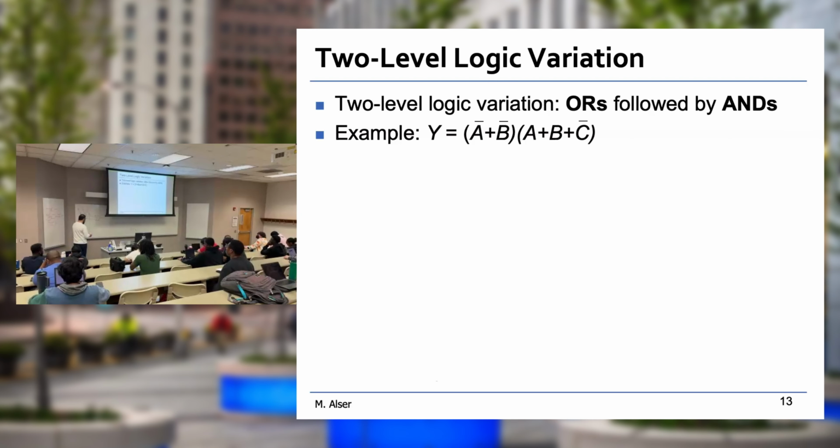Now, where's the second term? It's this one between the parentheses. So when I assume a 3 input gate is allowed, and then A, B, so we go with the blues, this first one, and then B, second one, and then the third one is C NOT. Since this is product of sums, we need to multiply these together. Remember, these should always be 90 degrees vertical wires. So take vertical and then vertical again, 90 degrees, 90 degrees, and this is the output as Y. This is how we implement this equation.